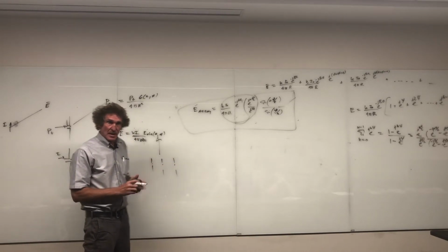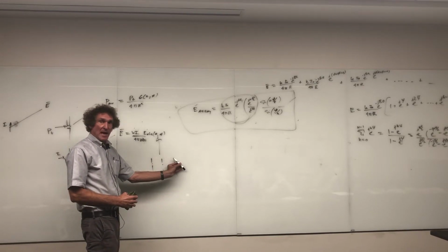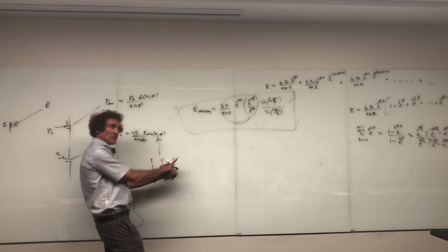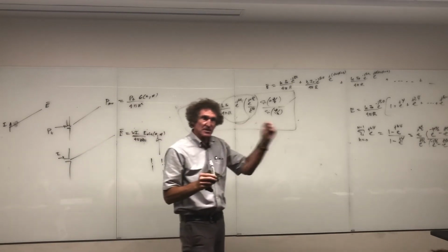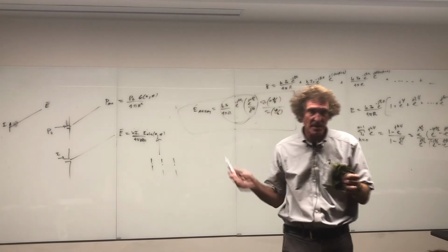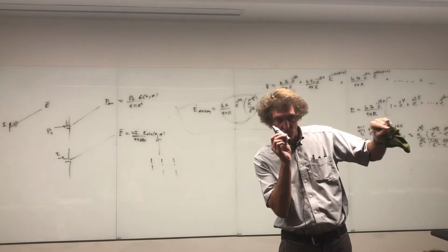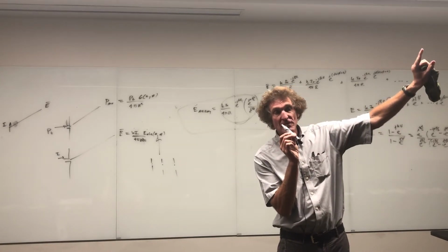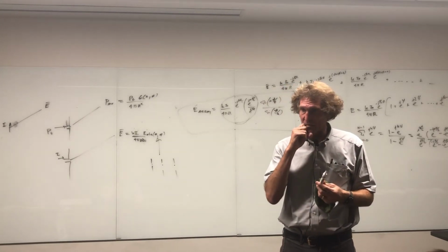That's important. Now, if they were oriented like this at 45 degrees, the maximum power would still be at the 45-degree angle, but to get that, you have to change the phase progressively, and that's later on. We'll talk about that. It's always with the orientation of the maximum power from one element. That will be the direction of the array's maximum power. The amplification possibilities can be a maximum in that direction. Comes later.